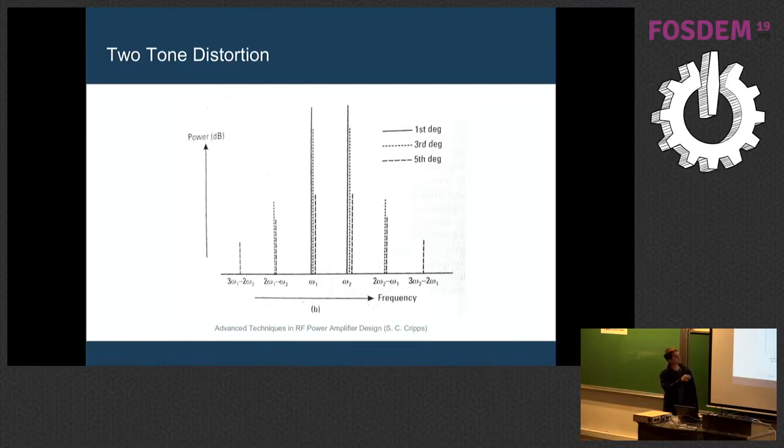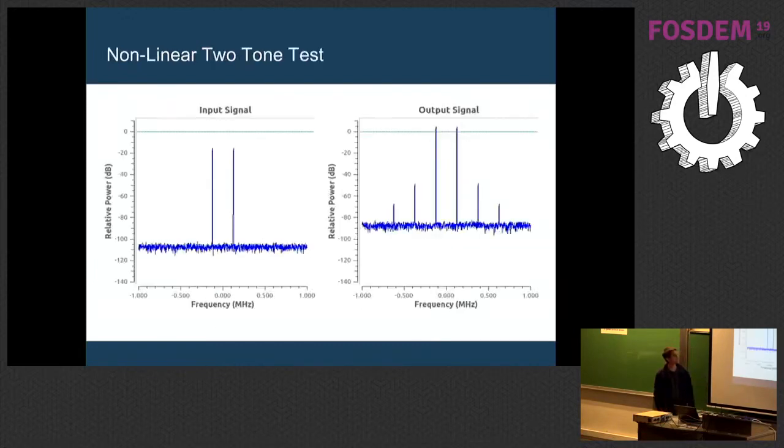And you can see that's not only true of the fundamental, it's also true of the third order, the primary third order distortion, but it also has a contribution from the fifth. And then the fifth is standing alone here, but you would also get the seventh order and the ninth order if you continued on. I just love that picture. I think it's really well composed.